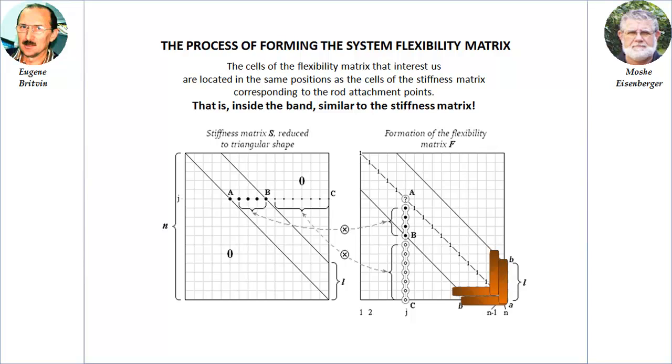Since the original matrix of the system is formed taking into account the unit reactions of the tested rod, we subtract from the reduced matrix the eigenstiffness matrix of the rod at the current value of the longitudinal force. Add to the reduced stiffness matrix the eigenstiffness matrix of the rod as a function of the parameter alpha. Find the eigenvalues of alpha.